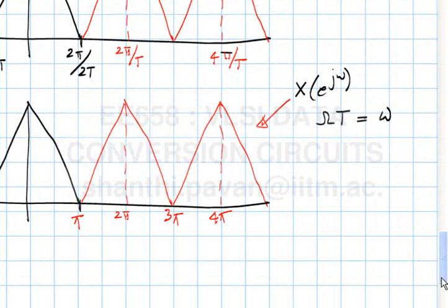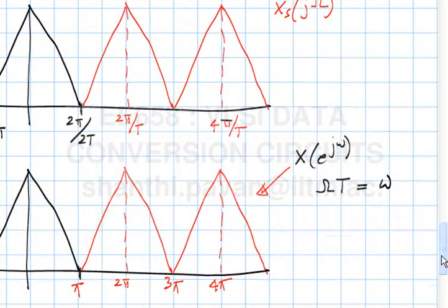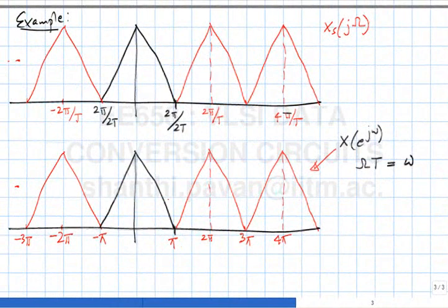And as you can see, this situation corresponds to a sampling rate which is exactly the Nyquist rate. So when you look at the discrete time spectrum, you see that it occupies the entire range from minus pi to pi, or 0 to 2 pi. There is no hole in the spectrum at all. If you sample this at a rate any smaller than 1 over T, then you will find that these aliases will all overlap, causing some aliasing in the spectrum.